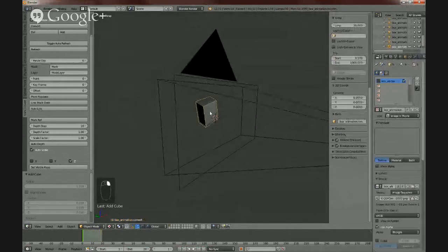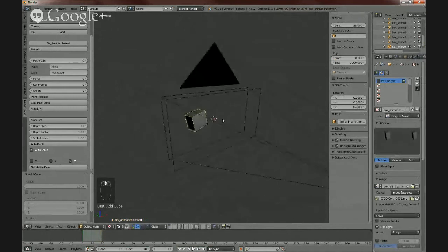Go back to 3D view. Select my mesh. And then I'm going to go make some quick adjustments to the auto depth calculation. So I'm just going to drop this down from 10 to 5, which will make the depth build more accurate.